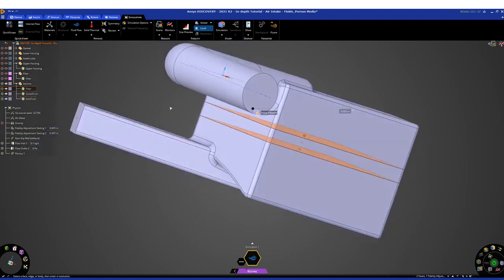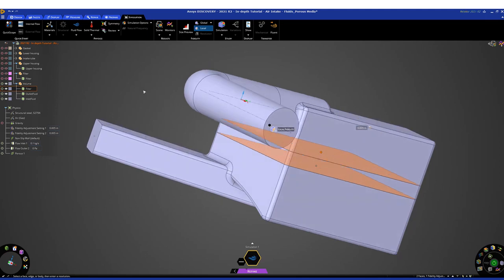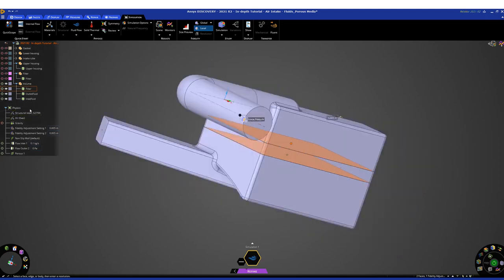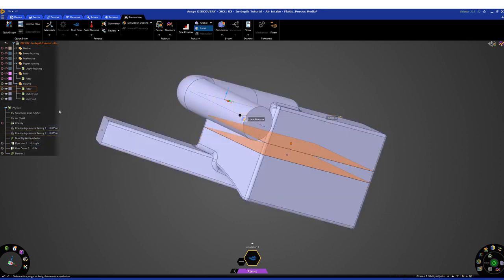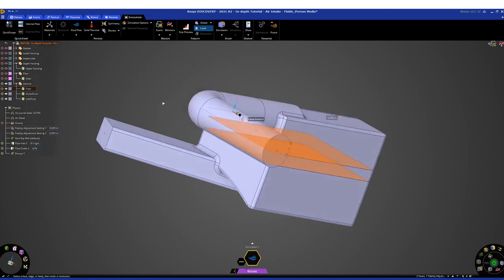And then you see also that these mesh settings show up here in the physics tree. So all properties related to the simulation settings, boundary conditions and mesh are located in this. But you also get the view of all the geometrical parts up here in this region. So we are almost set, but left to do is also to add some monitor points.